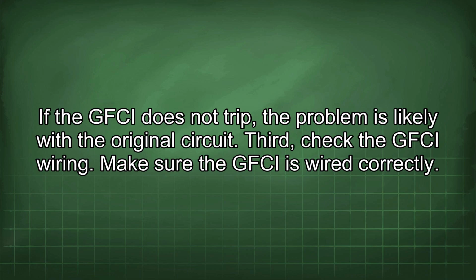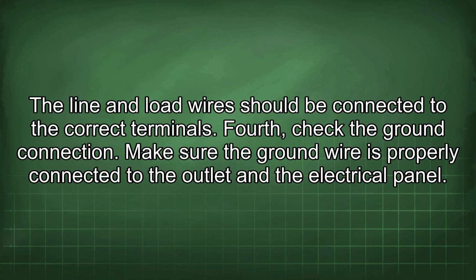Third, check the GFCI wiring. Make sure the GFCI is wired correctly. The line and load wires should be connected to the correct terminals. Fourth, check the ground connection. Make sure the ground wire is properly connected to the outlet and the electrical panel.